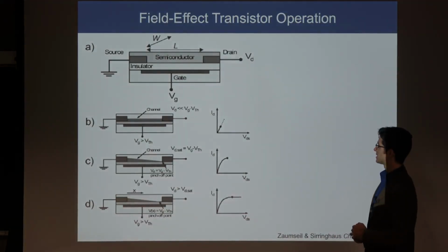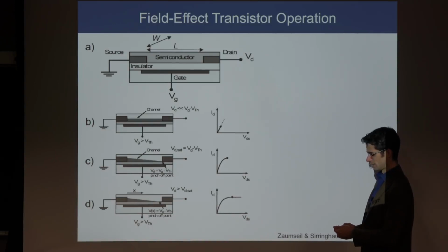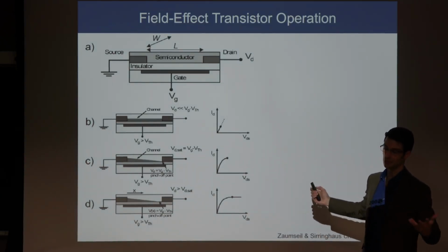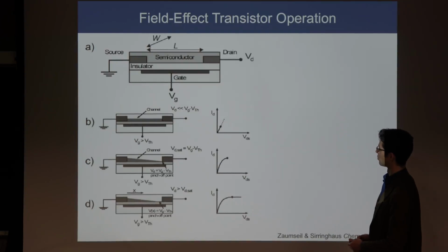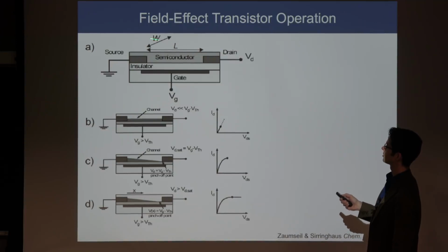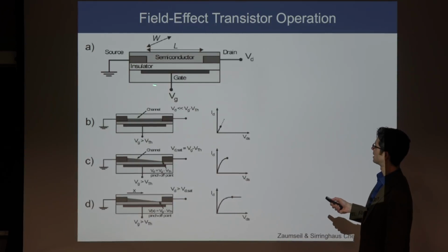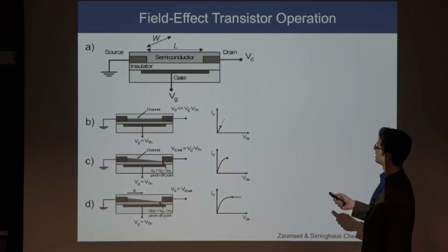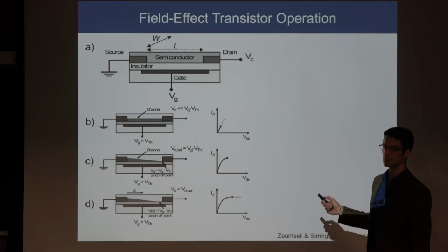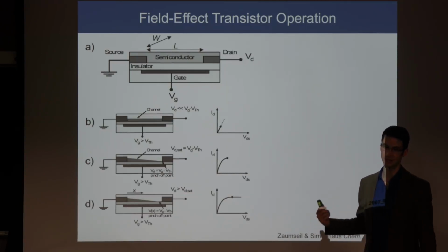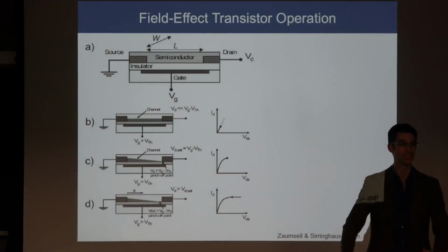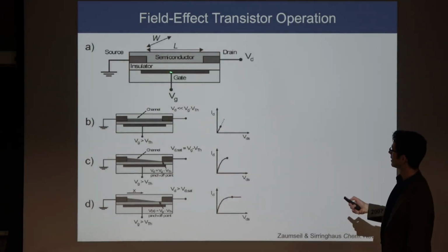Okay, so let's talk about organic field effect transistors, and not just any type of field effect transistors, in a little bit more detail. So this is a schematic diagram of an FET, and we met this earlier in the course when we were talking about semiconductor manufacturing. And you have some substrate with a conductive gate, an insulator. This is called the gate dielectric. Then you have some semiconducting material, which is sometimes called the channel, although strictly speaking, the channel doesn't form until you apply a voltage to the gate electrode.